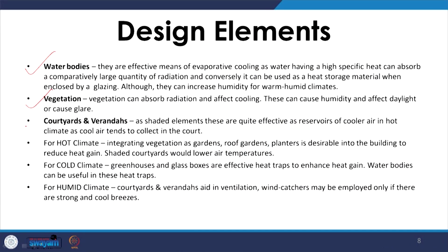Then we are also looking at courtyards and verandas as design elements. Now, courtyards and verandas are used for shading, for cutting off the direct solar radiation in buildings. So, they are more preferable in hot dry climates.